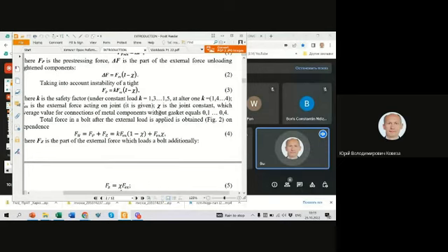Recommended values is from 0.1 up to 0.4. Let's take it 0.3 because for steel bolts it's approximately from 0.2 up to 0.35. So 0.3 is approximately the same for all. And write down these parameters